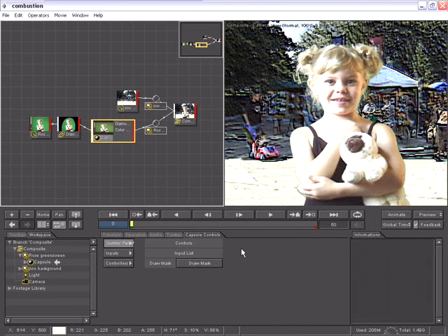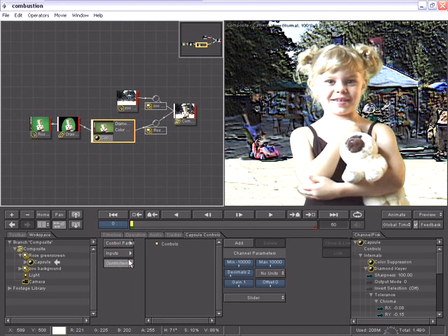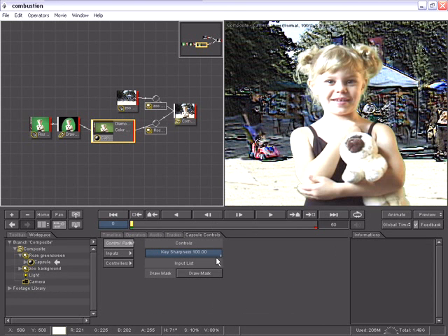capsule controls again. You'll notice on my control panel I have no controls right now. But if I go to the controllers, you'll see along the right-hand side, here are all the channels that I can access for controls of each operator, whether it's the color suppression or the Diamond keyer. If I want to add a control slider to control just the sharpness of the keyer, I can select that and then click Clone Link. And you'll notice over here in my controls, a new control has been added. I can easily rename this if I want by naming it Key Sharpness, hitting the Enter key, and when I go back to my control panel, you'll notice now I have a slider to adjust and control that parameter.